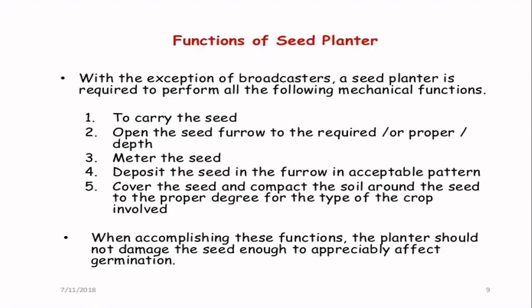Function of a seed planter. Mostly planter, seeder, and transplanter are similar, but there are some differences. With the exception of a broadcaster, a seed planter is required to perform all the following mechanical functions to carry out planting: open the seed furrow, meter the seed, deposit the seed in the furrow in an acceptable pattern, cover the seed, and compact the soil around the seed to a proper degree for the type of crop involved. By accomplishing these functions, the planter should not damage the seed, which would have an appreciable effect on germination.